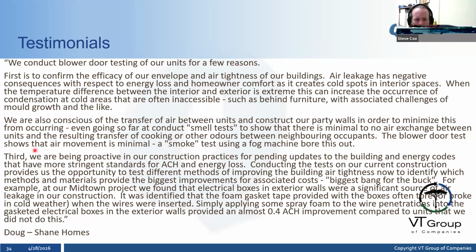Blower door test shows minimal air movement. A smoke test uses a fog machine, and we were helping them out with that when we did the smoke testing. We filled one unit up with smoke, depressurized another unit, and then we could see where the air leakages were more effectively. And then third, being more proactive in construction practice for pending updates to the building and energy codes that have more stringent standards for ACH and energy loss.